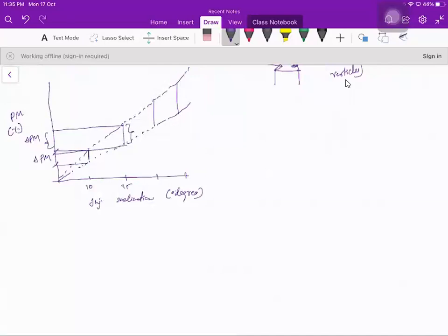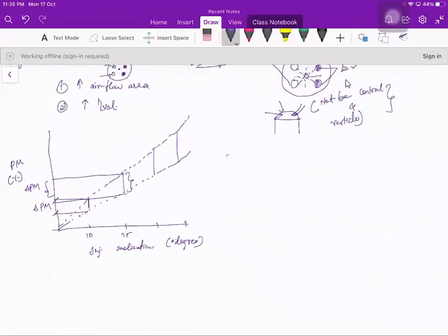So a centralized combustion system results in reduced formation of PM and NOx, giving lower particulate matter and NOx compared to the other oriented type of fuel injector.